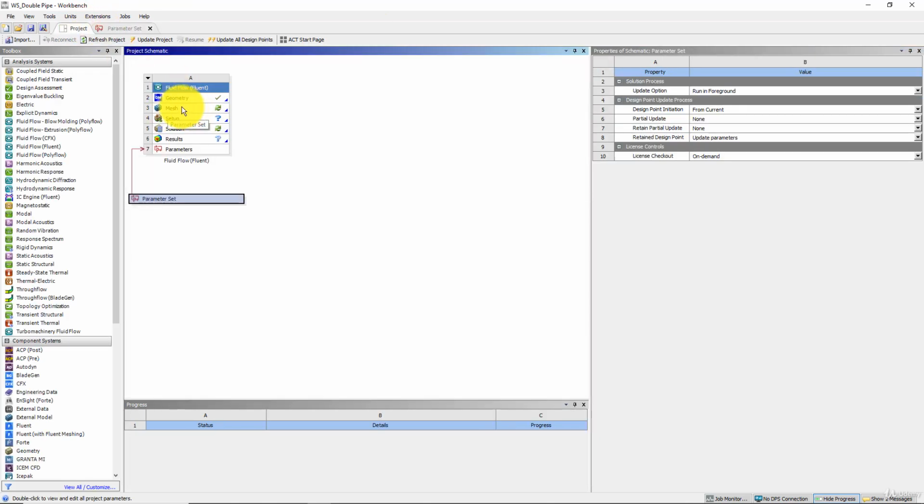And this will change the mesh properties for the second case, third case, and then for setup it will read the mesh, same boundary conditions, same other conditions, turbulence model. And this will solve the case, and it will give you results in the required format as you set in the CFD post. And if needed, you can also make one design parameter as the output, for example the velocity at some location, and this will be displayed on the screen here.